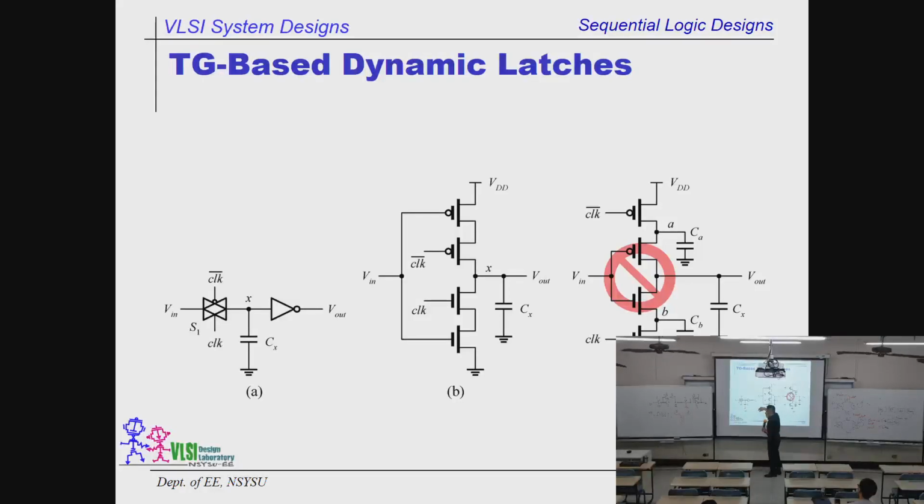So we have 2 transistors, we have another 2, and then the inverter here is split into 2 parts, just like this one. So when the clock is high, this one is low, so both of them are on. Then the V in will be inverted by the inverter over here to become the V out. So basically, these 2 functions are the same. They have the same functions. And this is called the clock inverter. But this one cannot swap both of them.